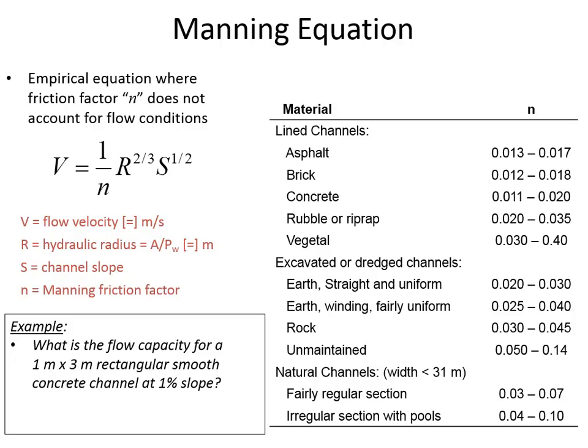Good question. So the cross-sectional area, 3 square meters divided by the n value, 0.011, hydraulic radius to the 2/3 power, slope to the 1/2 power, and you should get a flow rate of 19.4 cubic meters per second. So on the scale of difficulty, problems where you're asked to find the flow rate are about as easy as they get with Manning's equation.